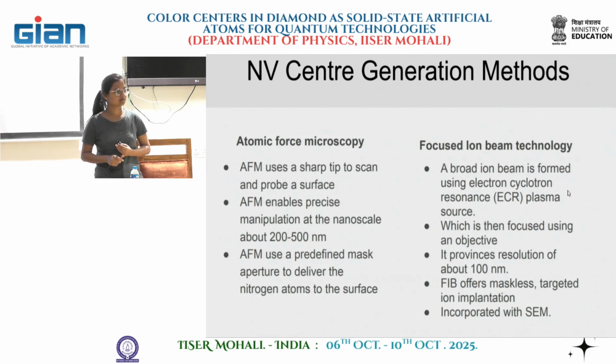in contact with your sample, or just a little bit above, and then you implant through this hole. And then the idea was that you move, and then you do another implantation, then you move and you do another implantation. But the problem is that it's very hard to control the array. It was very hard to control the tip. It was also very hard to control where the hole actually was. So this was not a very reliable technique. But somehow it allowed higher resolution than the one that we had, which was something like 150 nanometers.